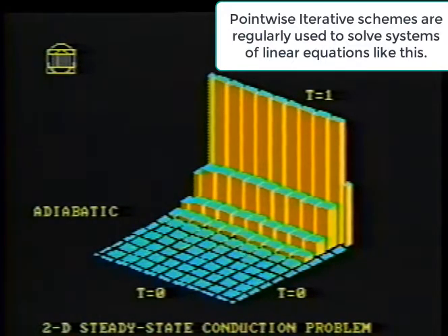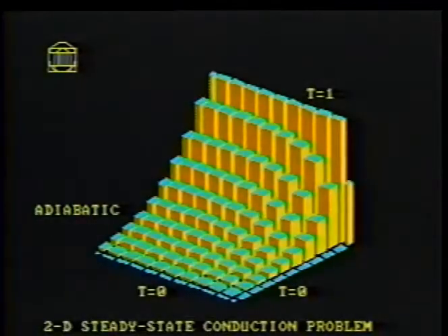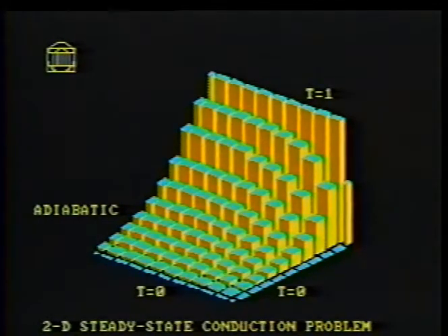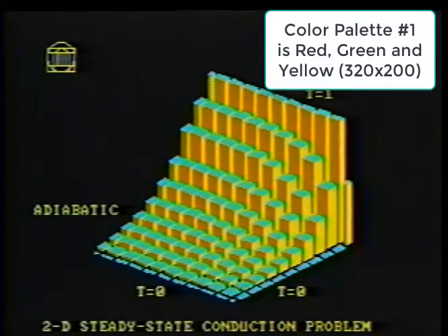Out here in the foreground, nothing much happens originally, and so we can come back and look at it in a couple minutes. Now we're in the final sweep, and you can see that the changes are pretty small. The boundary condition over on the left, that it be adiabatic, is nearly satisfied. That is, the temperature gradient there is nearly 0. And you can see that it's almost converged.